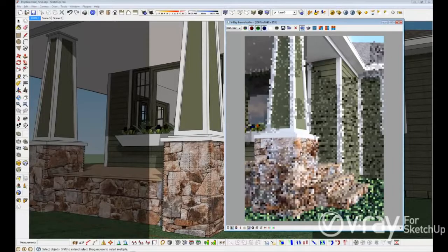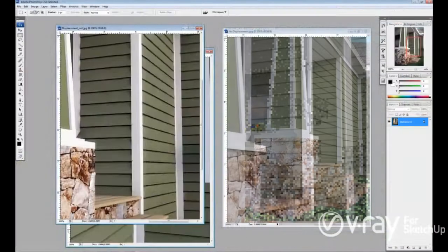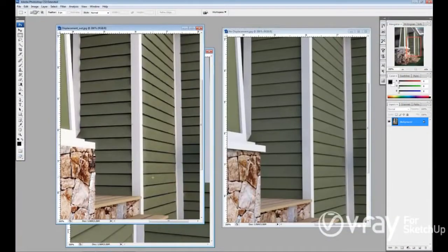The rendering time and quality of this image is more than acceptable. During this rendering process, you can see that the rendering buckets calculate quickly and with high quality. The edge length is set to 12. The final image has excellent edge deformation to define the wooden boards, and excellent detail in the surface of the wooden boards.